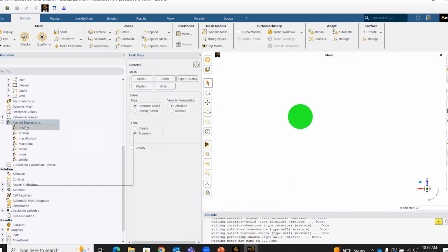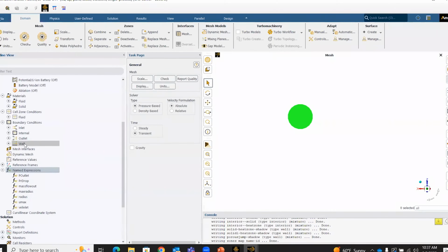If you hover over these, they will give you more information about what you've defined. They'll tell you whether it is single valued or constant valued. It'll also give you the final SI dimension for the expression so that you know where it can be assigned.